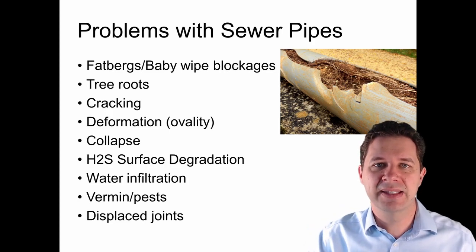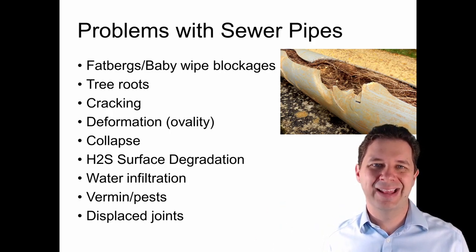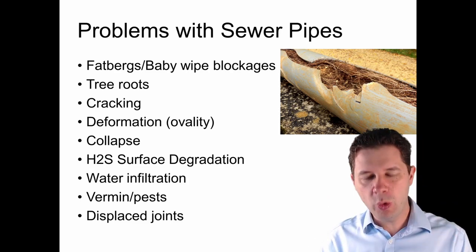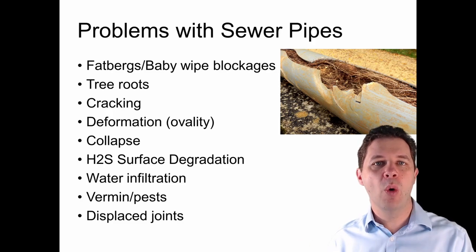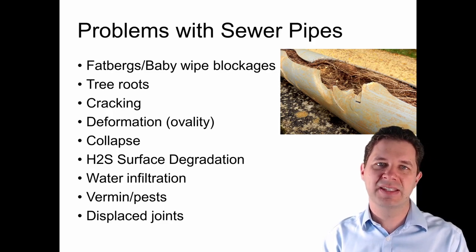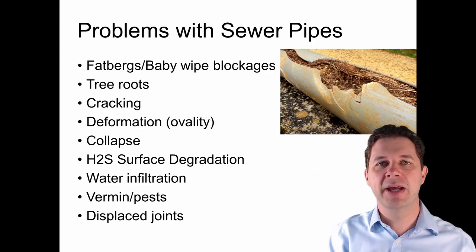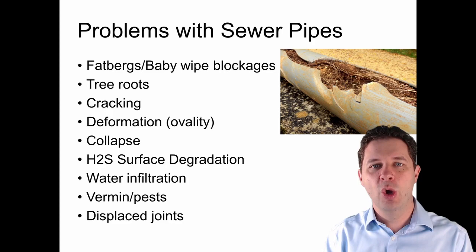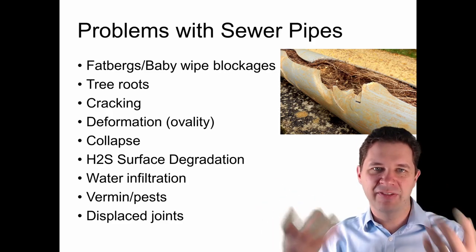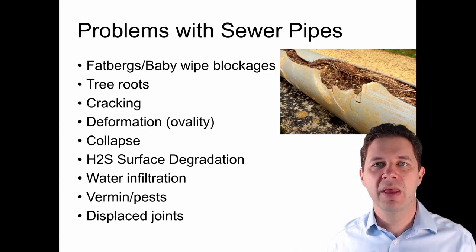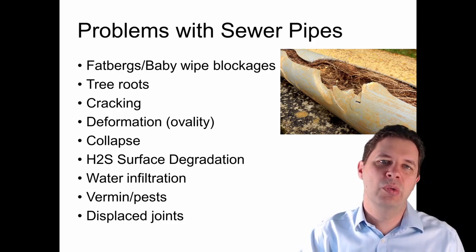But if we have big water events, like a whole lot of downpour of rain, a lot of that rain makes its way into the sewer system by finding cracks, or finding joins between sewer pipes, or even through the maintenance holes. There's a whole lot more water that needs to be pumped along in our gravity fed systems from sewer pump station to sewer pump station, and also going into the treatment plant. This can cause our sewer systems to overflow, and we can start getting raw sewage coming back into the environment out of manholes or through areas where the sewer's been affected. So we want to be able to measure that and work out what's going on there.